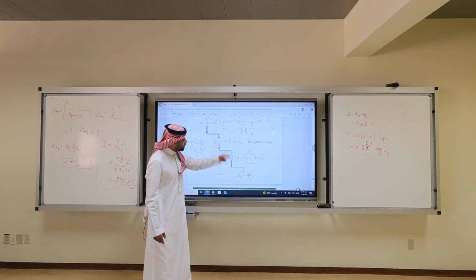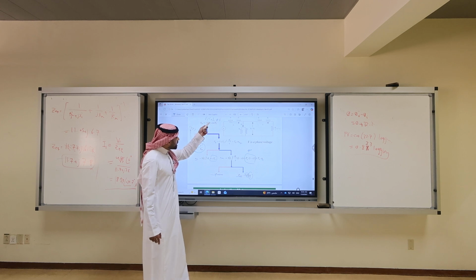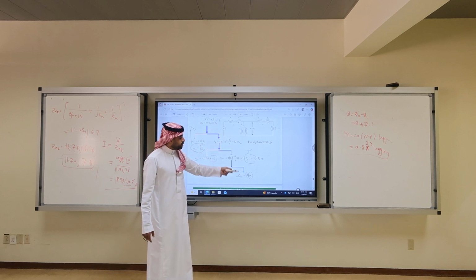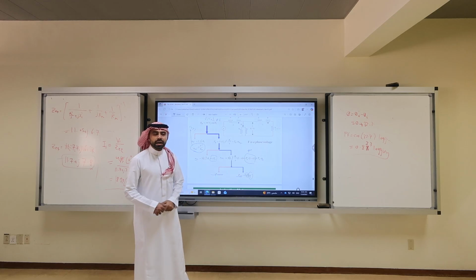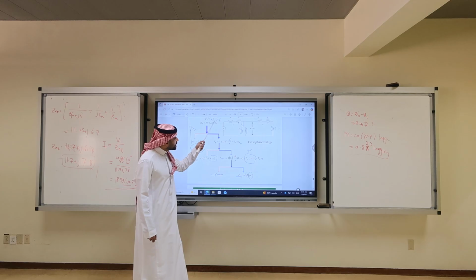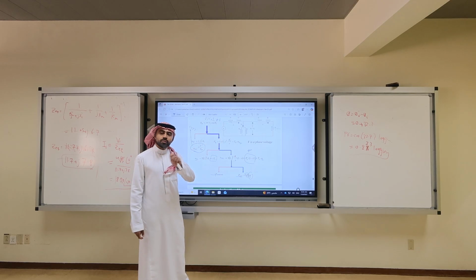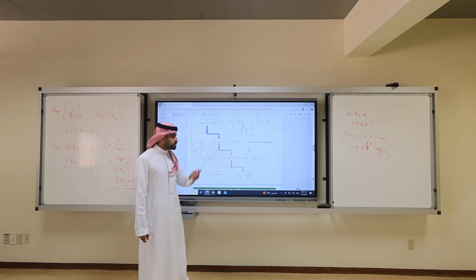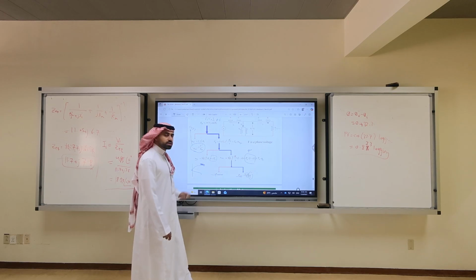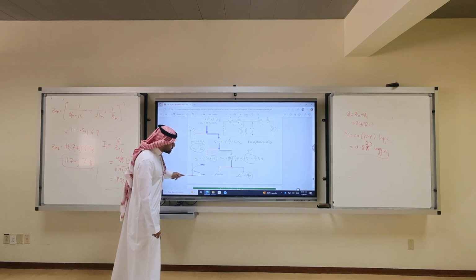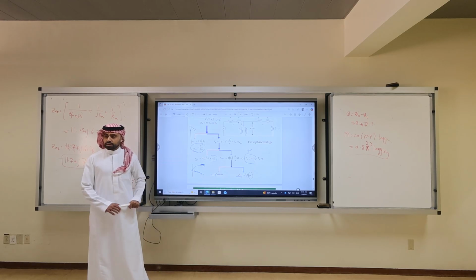The current gives you torque. So push as much current as possible in your machine and you will get the highest torque. But conservation of misery. Why? Because if you have so much current, the machine will heat up and you will have more losses, but most importantly, you might reach saturation in your BH curve. Do you remember the BH curve? You don't want to go into saturation. If you increase I, you increase H. Is it clear, Omar?